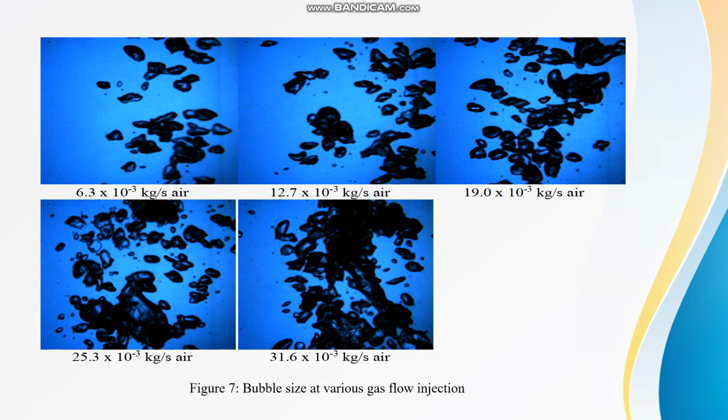So with an increase in gas flow rate injection into the bubble column, the coarser bubbles are immediately released from the sparger's holes because of high buoyancy, and the bubbles face more resistance to move in the upward direction as well as high residence time in the column. So this results in more mixing caused by the interaction of phases and hence an increase in mass transfer as well as turbulence in the column.